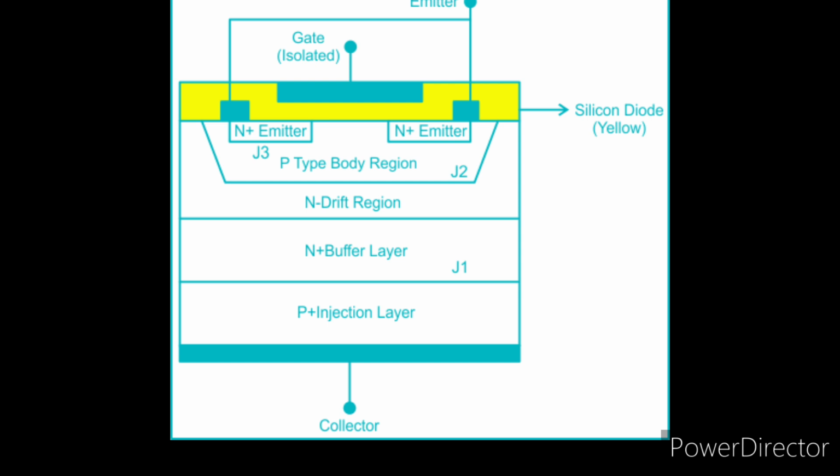the breakdown occurs at the lower voltages itself, which is not desirable. So remember, to act as an off switch, it should prevent the current from flowing even if high voltages are applied. Now everything appears good, but there is a trade-off here. A lightly doped region provides the advantage of blocking the high voltages in the off state, but during the on state, it provides high resistance, because of which the power loss can be high.